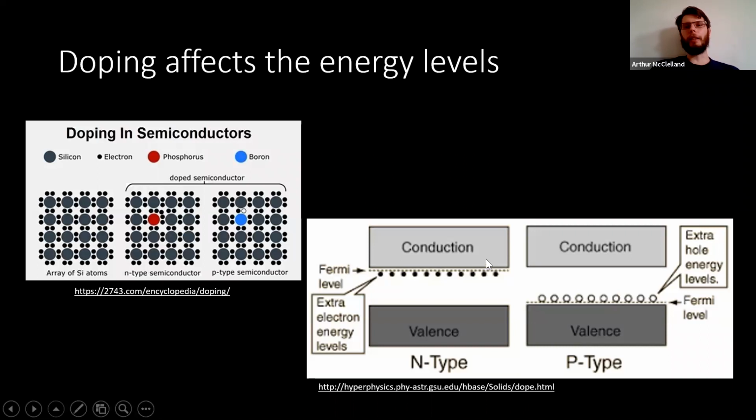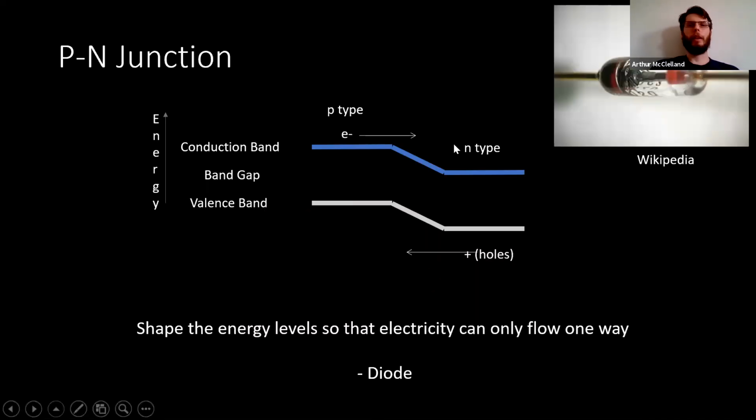And so if we take the N and the P-type materials and we put them together, we get an interface. And then at that interface, we end up with sort of an energetic slide. So the vertical is energy space, and the electron will go along, but then it'll see a lower energy level so it can go down the slide and go this way. The holes flow in the opposite direction. You can think of them as the bubbles. They're bubbling up and going this way.